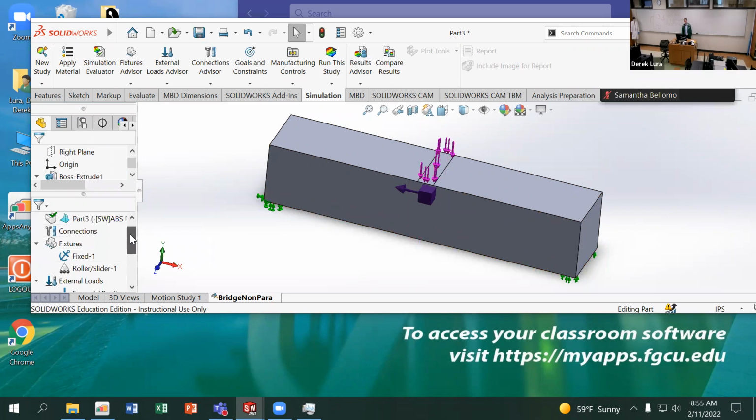The next thing you need to do is mesh and run this. I really, really recommend that you mesh and check the mesh size out before you run. If you just mesh and run using default settings, the chances of you getting a successful output from this is going to be really, really small. Again, if you don't have any idea what your mesh should look like, then go for it and iterate from there. But I really want you to mesh and then run.